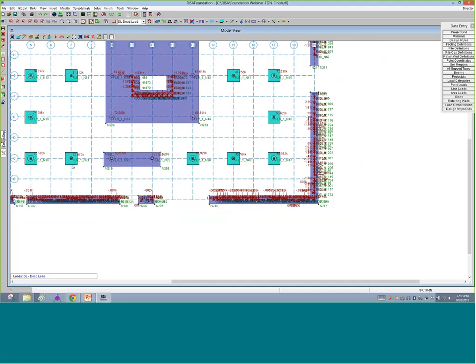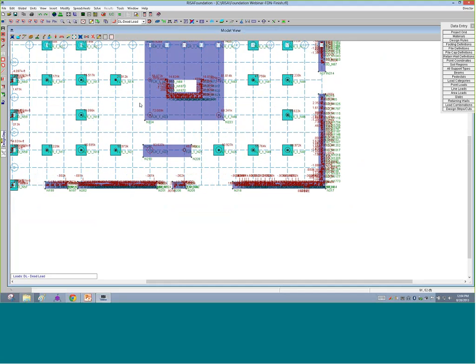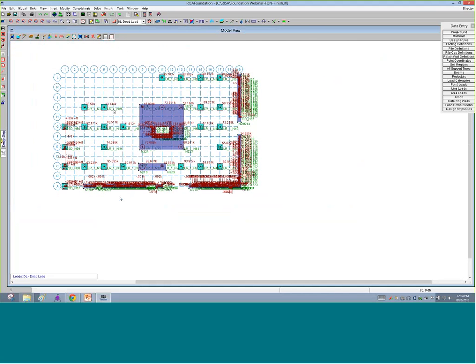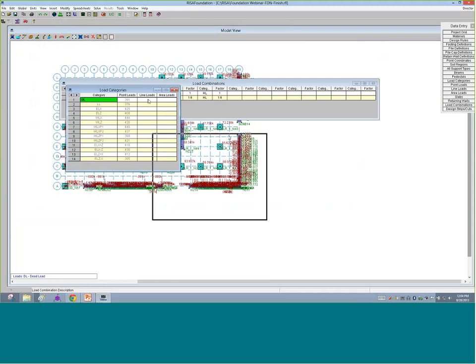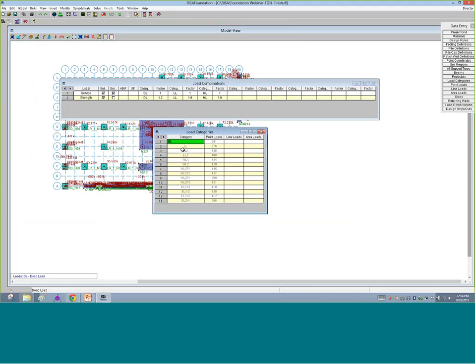This is going to be acting just like the footing is. The only difference here is that I'm going to be putting pedestals on it manually, and I would size it bigger or thicker manually. Slabs aren't typically bumped out in size because that wouldn't be something you'd want a computer program to decide for you. So you've got all of that different information. Because this came over from RISA Floor, I mentioned that you have all of those different categories, and you can see them listed out: dead load, live load, earthquake load, all of that broken out for you. So it's really well categorized for you.